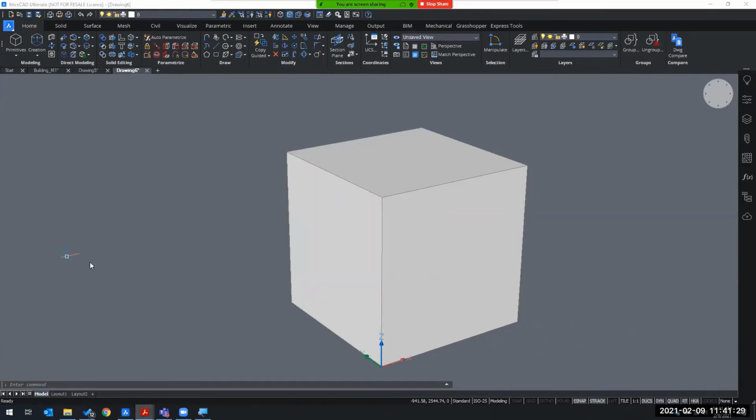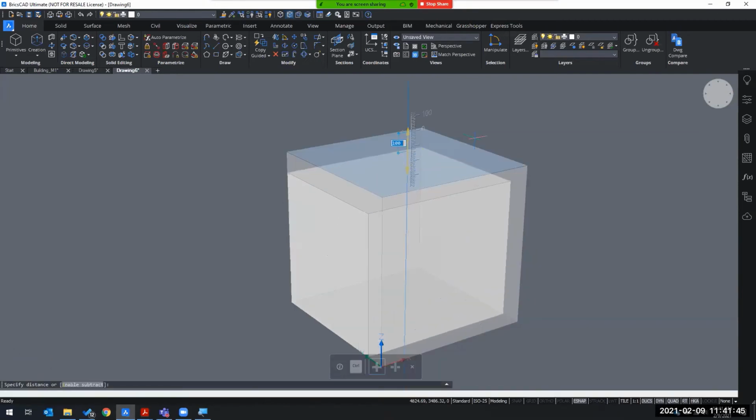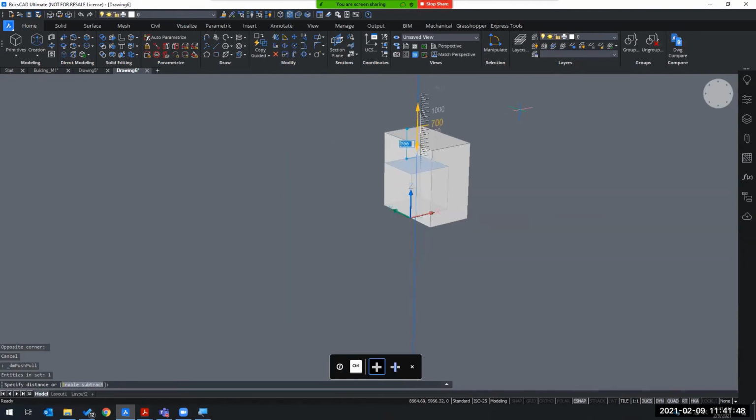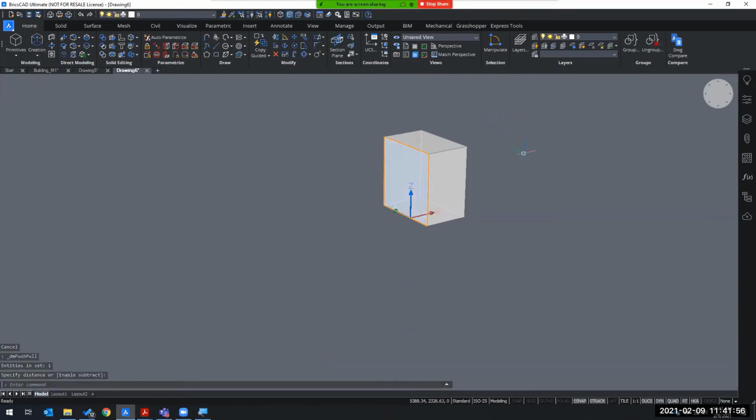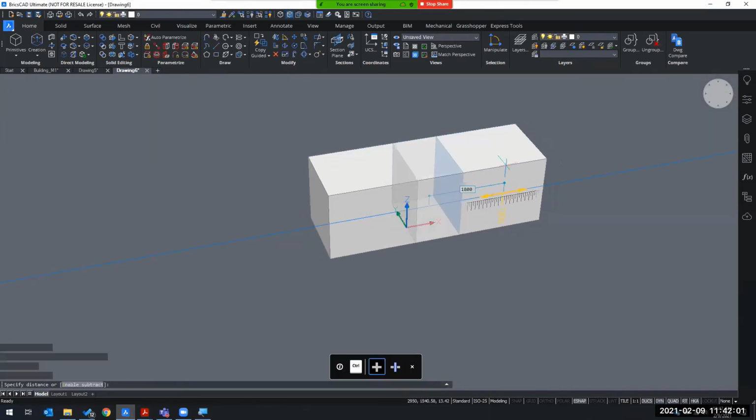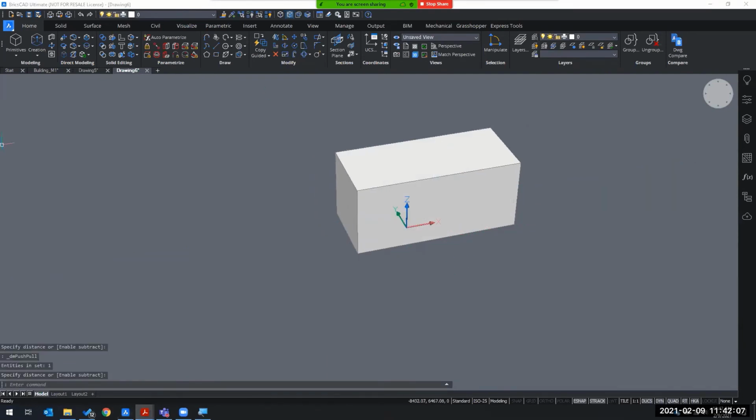Okay, manipulating multiple faces. I can also select 2 faces just like that by just clicking. I don't have to click shift or anything like that. I just can continue clicking. And something nice to know is, for example, if I click those faces and do the push pull, I can now put whichever distance I want, and they both are going to be extended the same way. It works also the same with this. So if I now, it would adjust those 2 at the same time. So that's handy also to know.